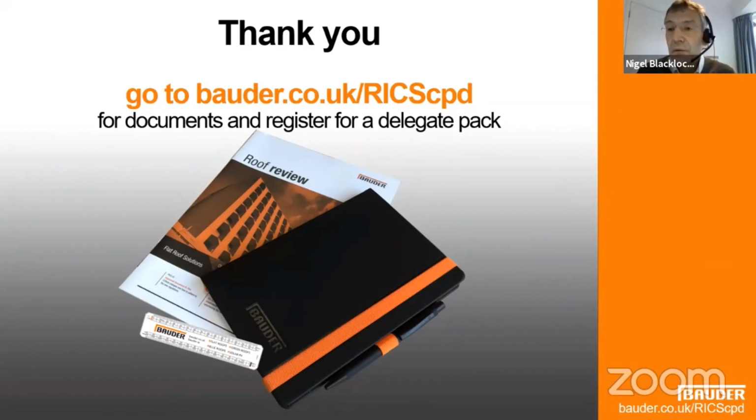So for instance, in the Bauder range, we have some there that we do achieve B-Roof T4. Some of them are very difficult to test. But you've got to realize that often there's a thick growing medium that's at least 50 mil thick, which would be the equivalent of the 50 mil thick of the stones and ballast. And it's typically going to be on a concrete deck. So the initial fire spread that somebody might be worried about would probably be a very quick flash across, especially if it's tinder dry. So hopefully that answers the question.